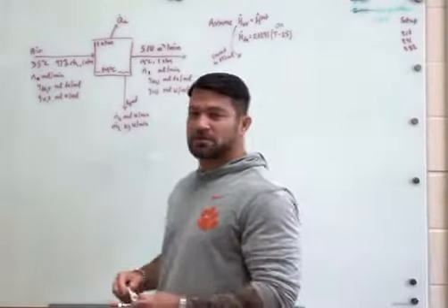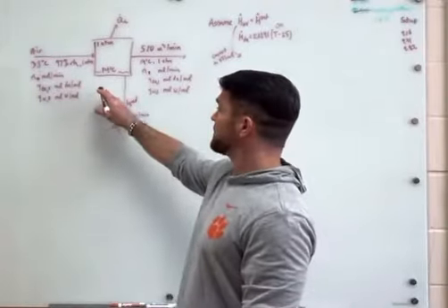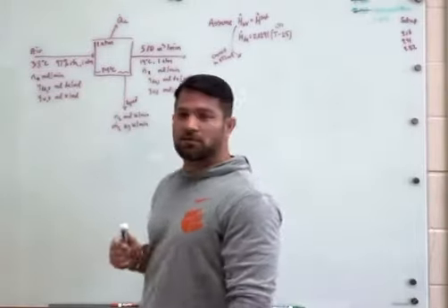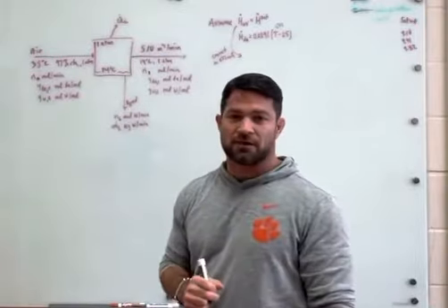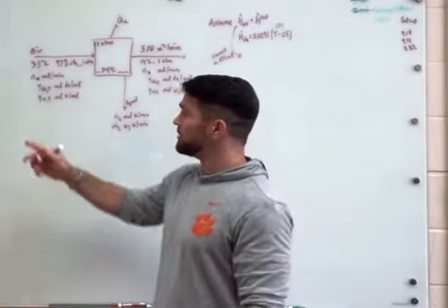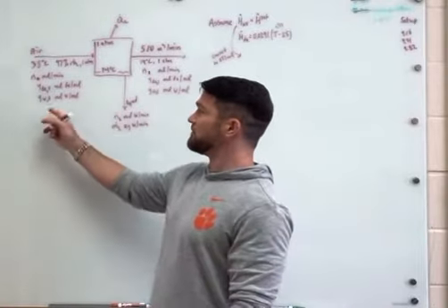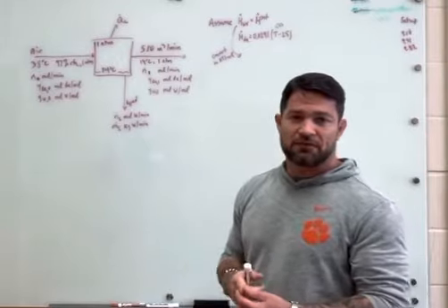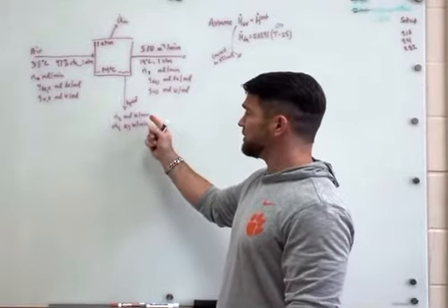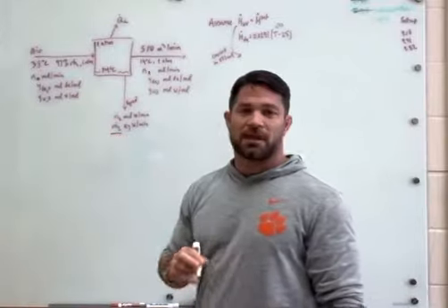I've already drawn and set up this process here. We have air at the given conditions entering the cooler, and some of the water is condensing, and the air is being delivered to a process at 510 meters cubed per minute. The problem didn't give a pressure, but I'm going to assume it's 1 atmosphere because we're just taking air from the outside. I drew and labeled it in terms of the total moles coming in, moles coming out, and the mole fraction, because we can use the definitions and saturation conditions to determine the mole fraction of water. I also labeled the moles of water coming out and the mass of water coming out, because this is one of the terms the problem asks us to calculate.